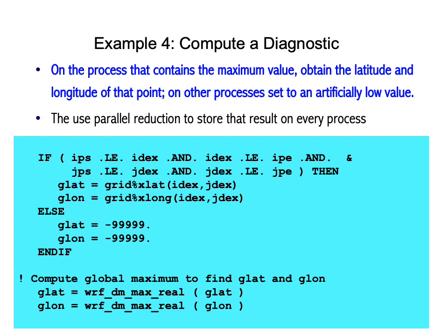If we simply wanted the I and J index value of the maximum wind speed, we would be complete. However, we've asked for the latitude and longitude, so it's going to be one more set of usage of internal WRF functions. This if test at the beginning is the logic that is used to determine which process actually owns that I and J index of the returned maximum value.